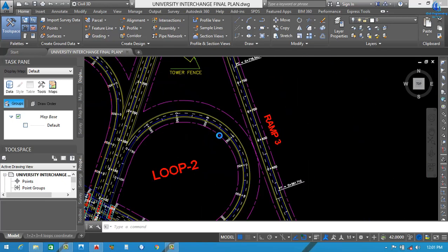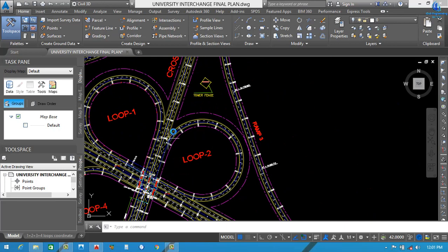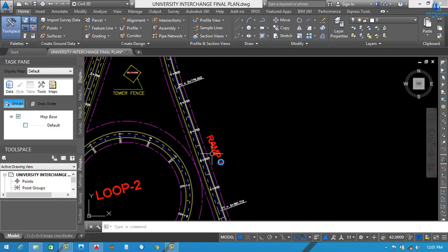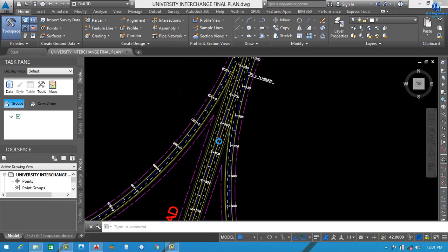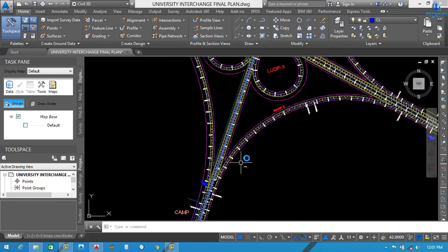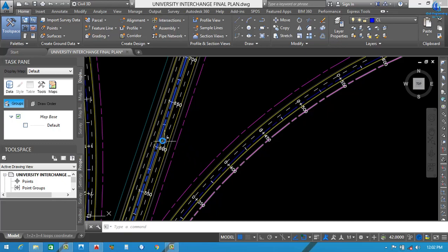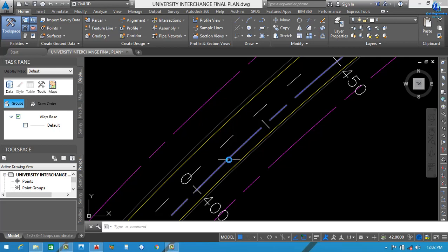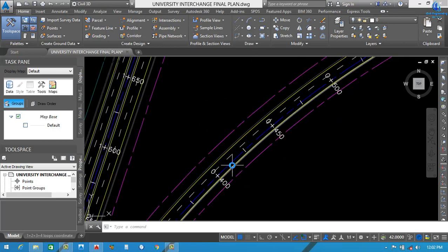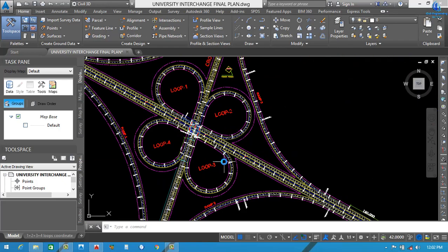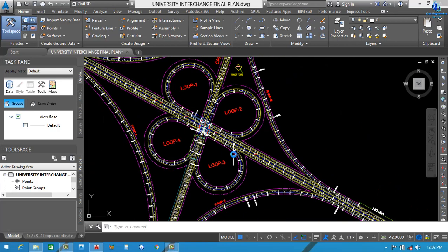These are loops. Okay, because basically these roads come from here and go to the other side by crossing its bridge. This is called a ramp. So everywhere you can see one alignment, and after that its other components are ready. Sometimes alignment comes in the center, and sometimes alignments come in the corner side. You can see one side, and this is the width, because this is one super elevation side slope. So now you can understand the importance of alignment in any road in any project.